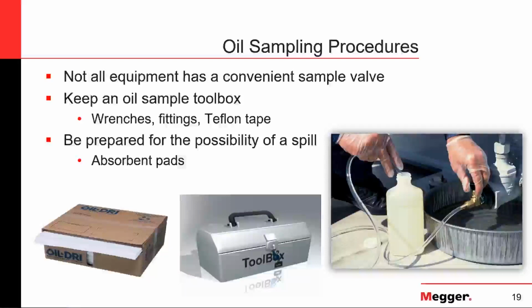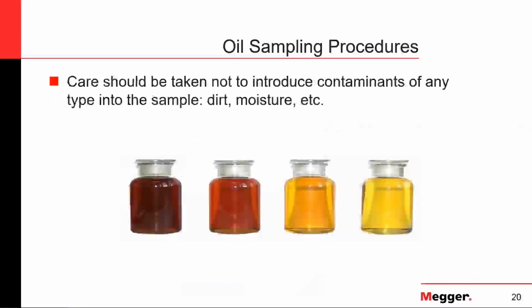Now, when we are out in the field, all of us who have been out there know that not every piece of equipment will have a convenient sample valve or very easy to install adapters so we can sample the oil. So we need to be ready with a sample toolbox, with tools, wrenches, fittings, Teflon tape, and sealants to reinstall the caps in the valves.